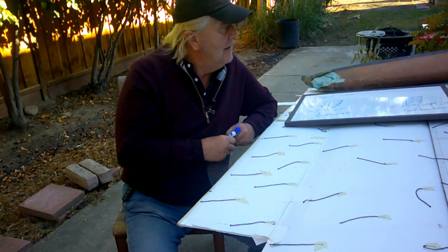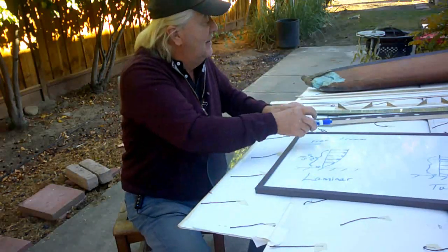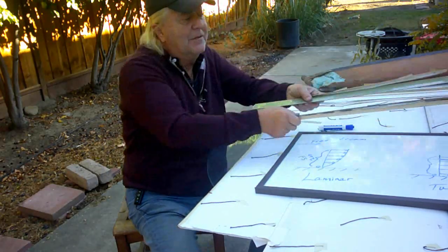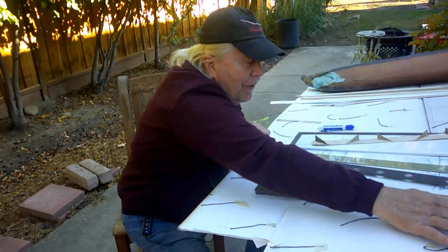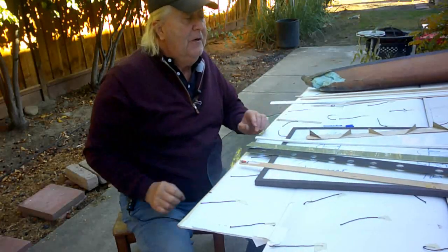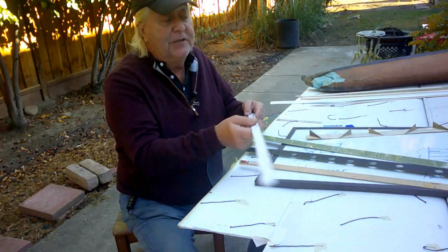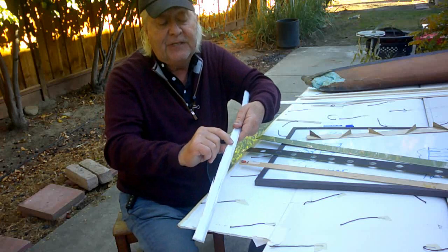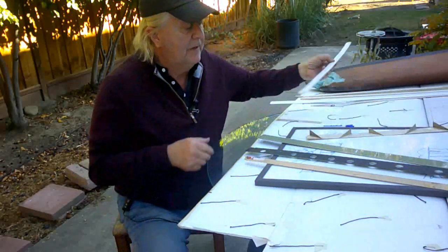And this, in fact, I tested 5 different types of trip strips all up here at the 1/3 chord position where the velocity is the highest. And I tested just a little ramp here, a 3/16 of an inch tall step like this. Okay.